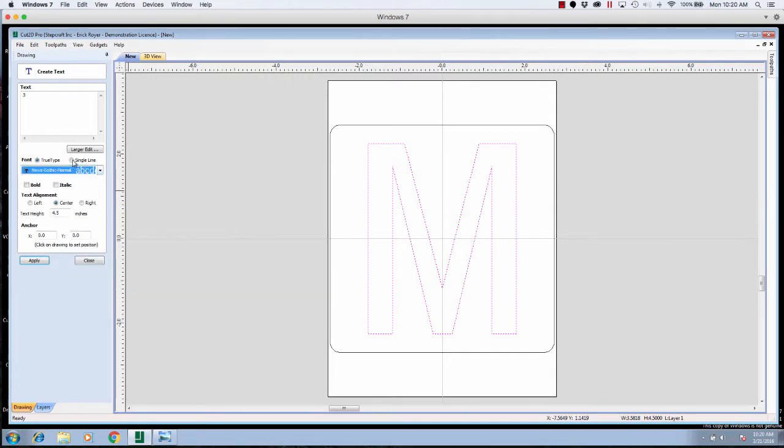So what we're going to do is we're going to click. Now the reason for this is if I took this font and I shrunk it down real small to make the number 3 in here, and I'm using an 1/8 inch end mill, the distance between the 2 lines of the font is going to be less than 1/8 of an inch. Therefore, the end mill will not cut it. If I try to pocket that, it won't cut it out.